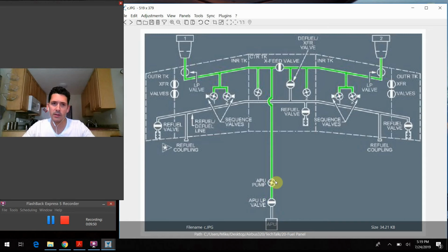In the case of, let's say, you show up to the airplane, there's no ground, jetway power hooked up to it, there's no power going to the thing at all. Well, just using the battery power alone, we need to have a way to get this APU online so we can establish AC power to the network of the airplane, and then we can power all these other pumps that rely on that AC power. So once again, I think it's a really interesting design concept that you can get this pump running without any AC power on the airplane, if that makes sense. So just to draw that all together, the point is you can start the airplane with battery power only and get everything going that you need to, and it starts with this APU getting up and running. So one little interesting thing to tell you about there.